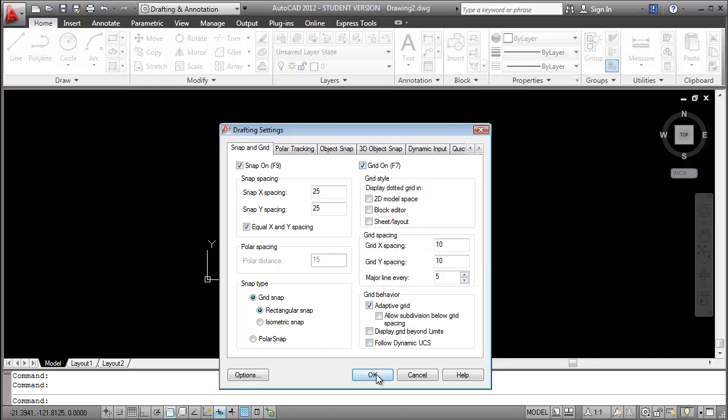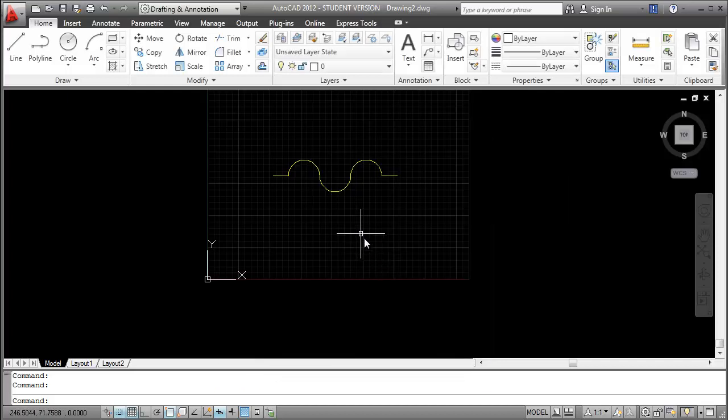So now if we click OK and see what happens, the screen changes. Now the object has a base point of 0,0, which is the origin, and that corresponds to the end of the line, which is there. Yep, that point is 0,0. So this would be the start point of the drawing.